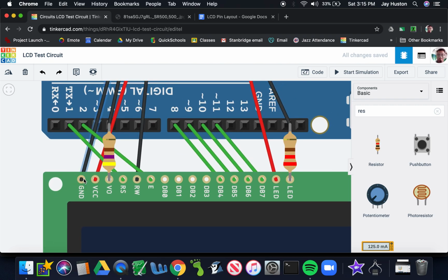That's for later. Just quickly walk through these pins and how I've wired them. Okay, pin 1, ground. That powers the whole screen, or is the out for the electricity in the screen. Pin 2, that powers the whole screen. That's the in for the electrons in the screen. Pin 3, what's that? Oh, that's contrast. That decides how bright it's going to be. So I'm going to be replacing this resistor right here with that potentiometer I just dropped in so that I can change the contrast.